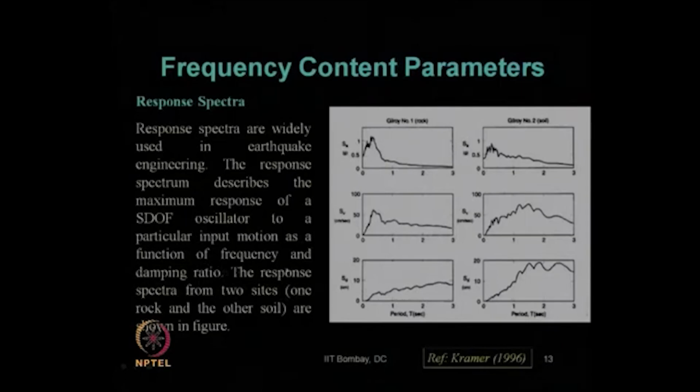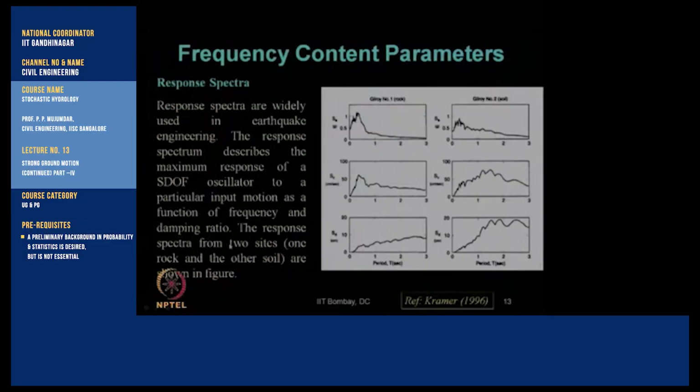So, as a function of the frequency, and it is a function of the damping ratio, because whenever we are finding out the maximum response, suppose the maximum displacement, we always express that maximum displacement as a function of the initial displacement, or in addition to that we use the value of the damping ratio. The damping ratio was a very important parameter. If you remember, it was a function of nothing but damping ratio, and what was the function?